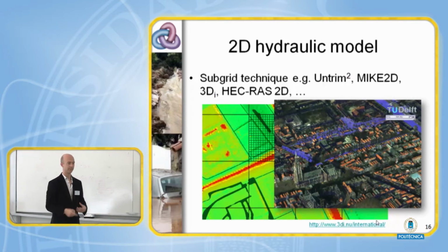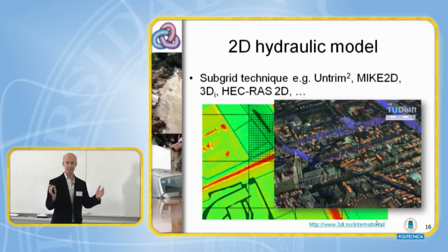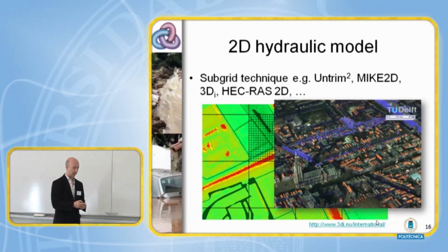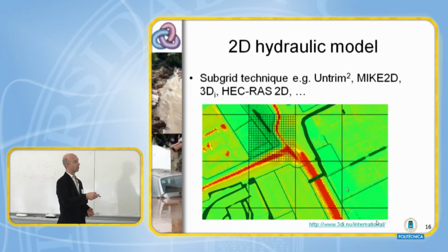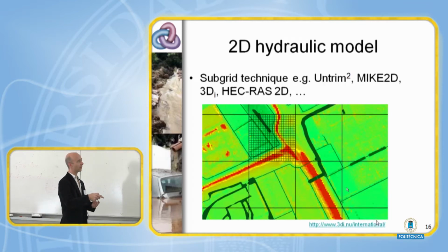So you can almost go to a resolution of maybe 10 centimeters, 30 centimeters, but try to keep the computational time of a much coarser model. They do that by solving the equations on the coarse grid, as I mentioned. So it has some drawbacks: this grid cell floods, but you don't know which part of the cell floods.